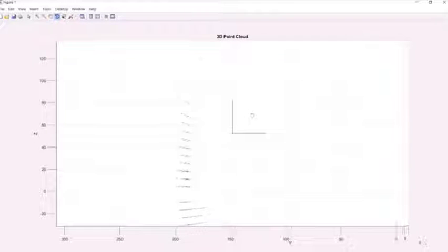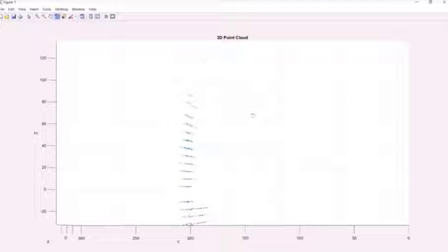The 3D point cloud generated for the back face turned out pretty well on the first attempt, with the exception of the overhang. Originally, I thought this was due solely to its dark color, which makes the laser light not show up very clearly in the camera lens. But I realized later this could be addressed by mapping the overhang separately, allowing the camera and laser to be slightly closer to this part of the target.